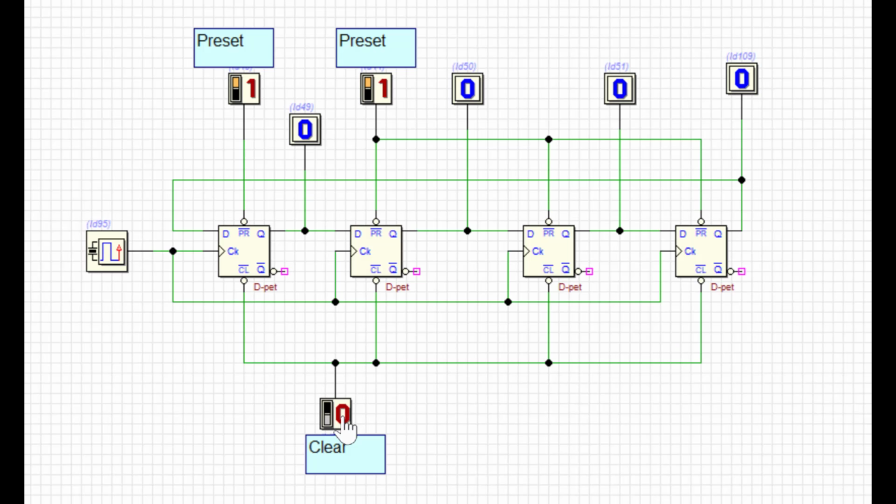Now let's run the simulation to test the remaining two lockout problem sequences. Now if you look here, 0 0 1 1 0, now two ones are circulating and this will be in this loop forever. Your two ones will be circulated within these four flip-flops. It will never go to the original sequence which we defined for the ring counter.